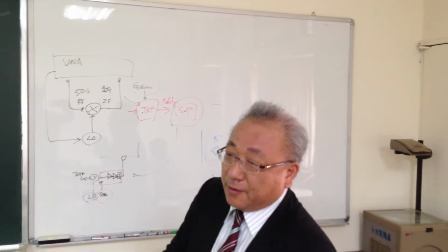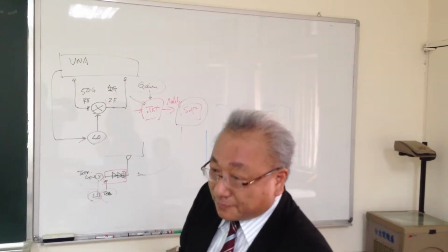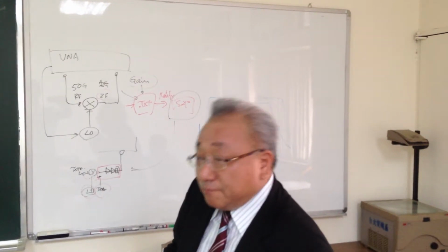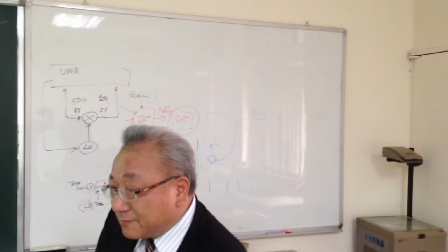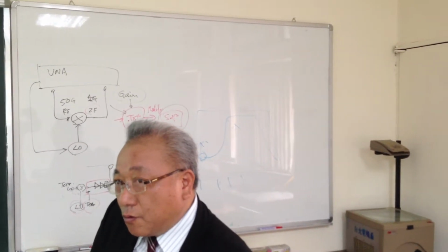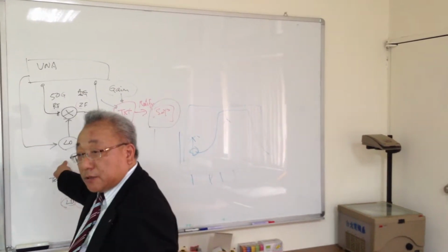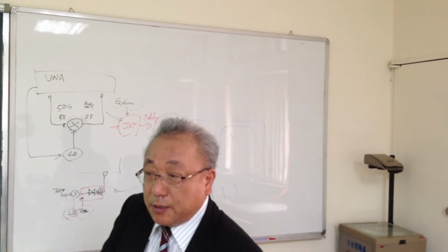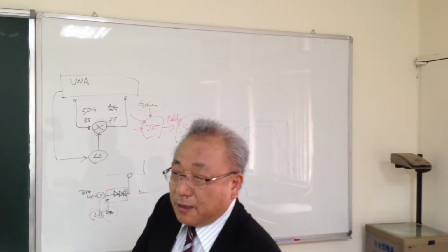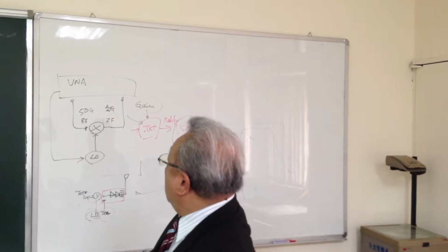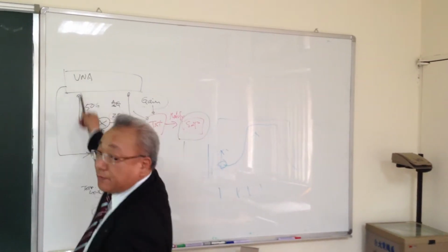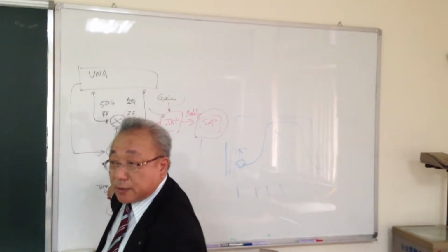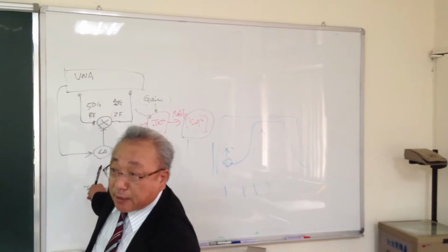In noise figure measurement of the mixer, it still uses the cold source. Cold source meaning like a local external source? We only have to inject the LO signal, no RF signal from the VNA. Okay, so we need an external source for the local signal currently.